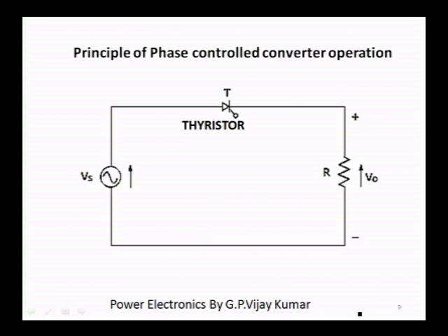The other requirement is we need to fire the SCR, we need to give the supply to the gate. One method of firing an SCR, already familiar, is gate firing using a gate voltage, or you can use a pulse also. Pulse triggering is also one of the methods. Usually in the lab we give a constant DC gate supply.